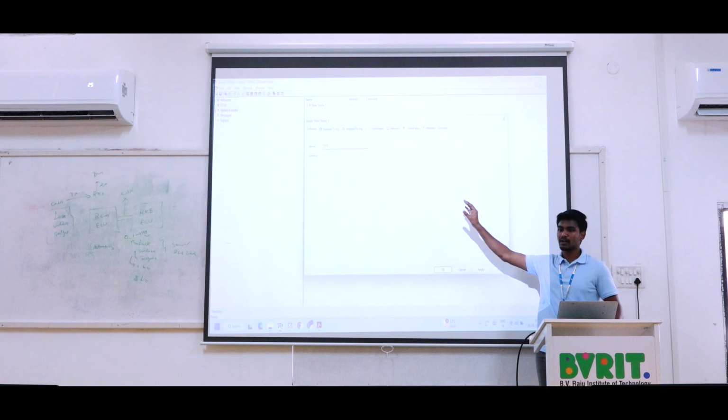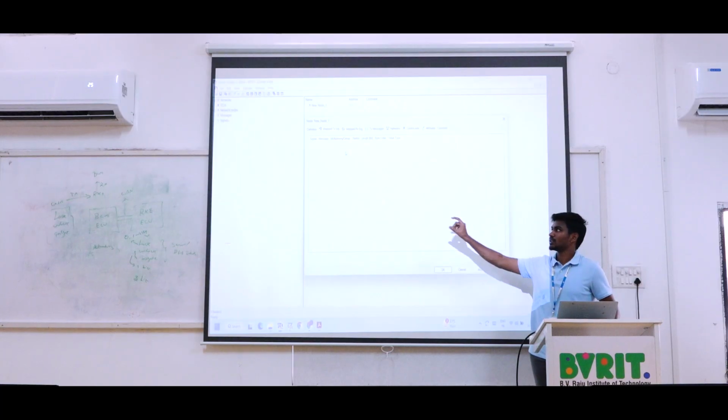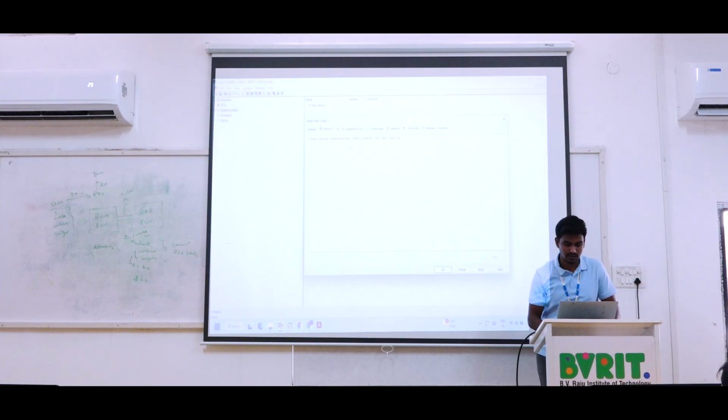Once I have created this, afterwards I will give you some time to click. So now I have created the RKE ECU. So what are the signals we are going to map? What are the signals it is going to transmit, and what are the signals for receiving? That is called the mapped RX and mapped TX signals.